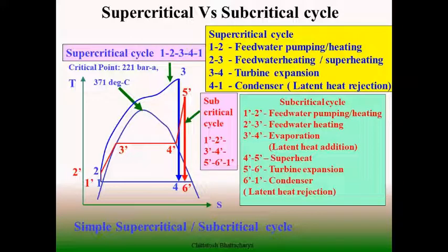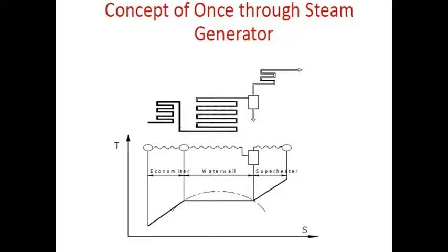Incidentally, it is not that all the supercritical units start from the supercritical regime only. All the startup operations are in the subcritical regime. So naturally there is a separating unit, a steam water separating unit, even with the subcritical supercritical boilers, and this separating unit continues to separate the water steam mixture, with a circulation between the evaporator tubes, the evaporator water walls and the downcomers.